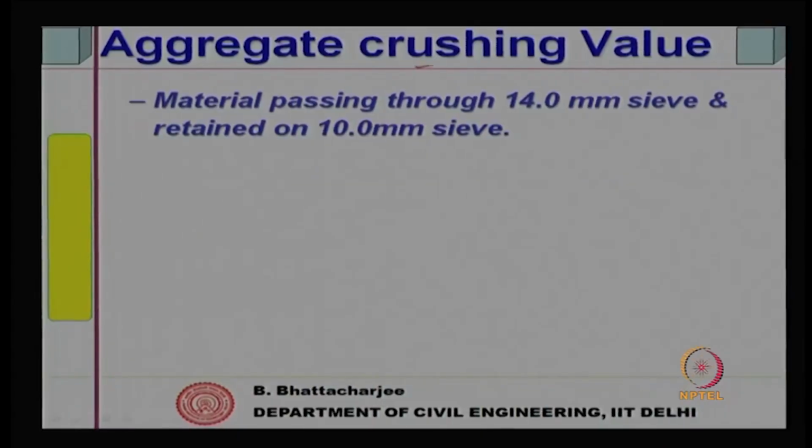Okay, now the properties of aggregates. The strength of aggregate is measured through aggregate crushing value. You see, parent rock strength is usually not relevant in case of concrete, because once you fracture the parent rock, its strength would be higher, because fracture has already taken place through the fracture planes. So, whatever is remaining must be stronger. Well, size effect sort of thing: the larger the size, the more probable it is to find a failure plane or fracture plane. Therefore, no point using rock strength in aggregate.